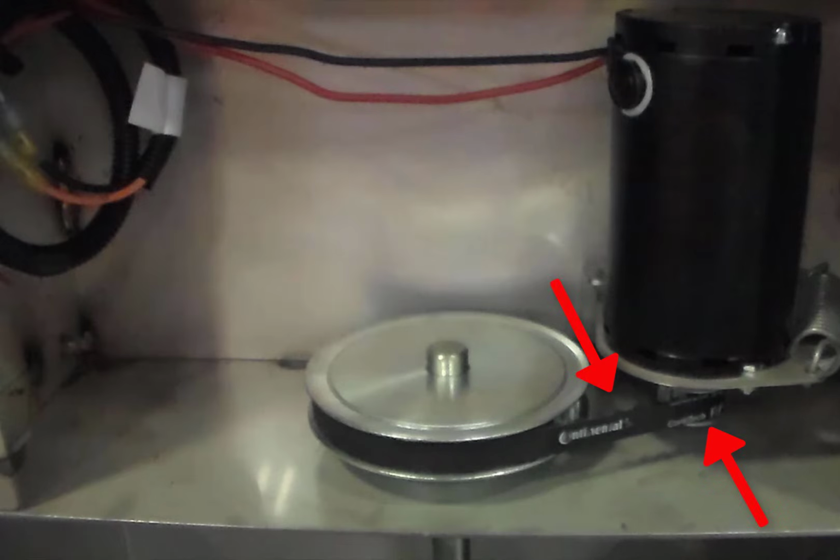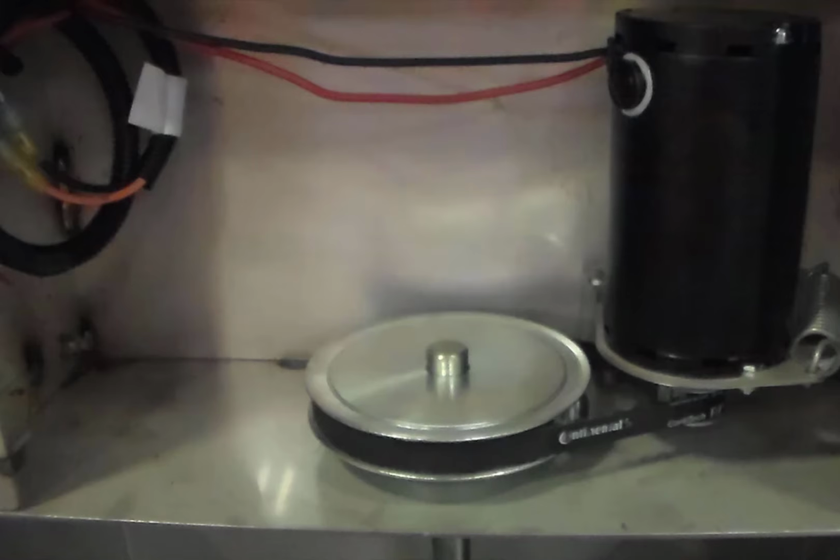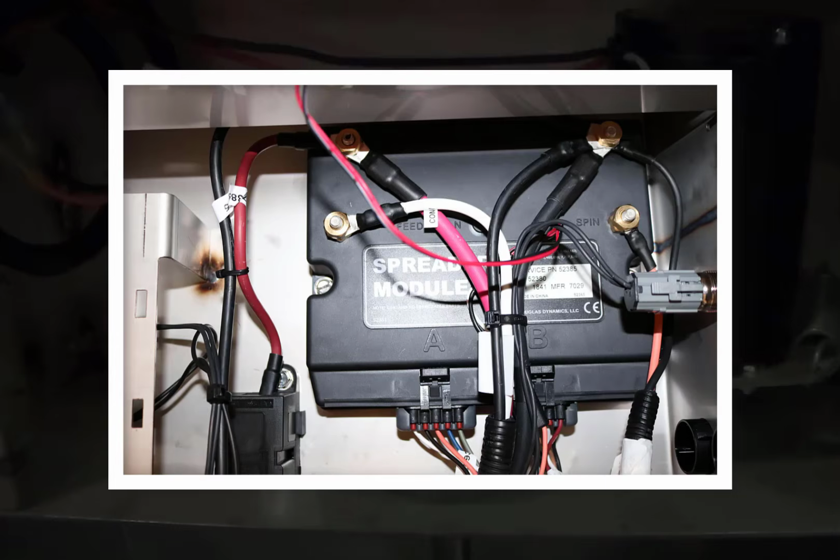Check the belt alignment and set screw on the electric motor gear. Disconnect the spinner motor from the module and jump power and ground to the motor to see if the motor works properly. It is possible that the motor is defective and needs to be replaced. Lastly, if everything tests out good, try replacing the spreader module or cab control.